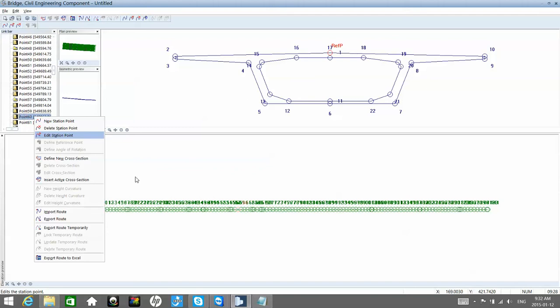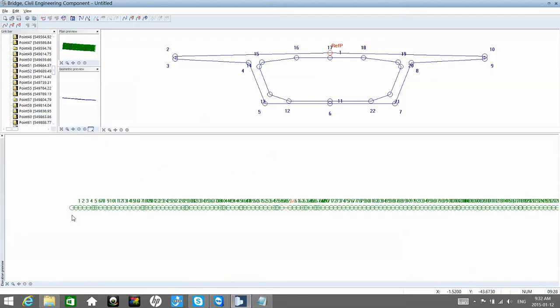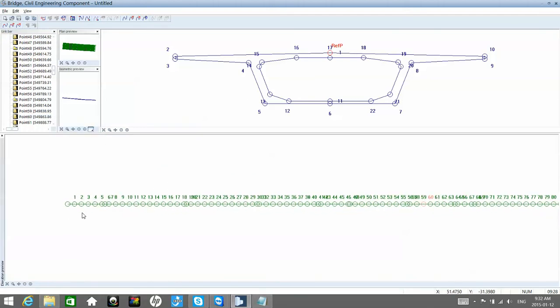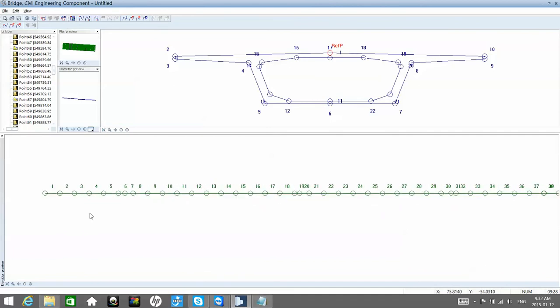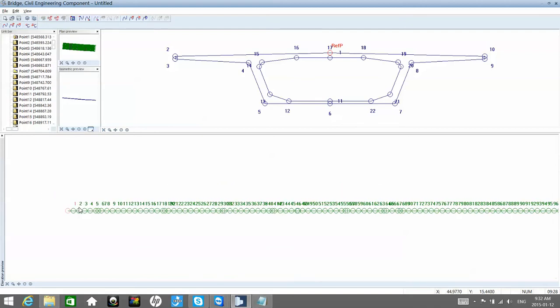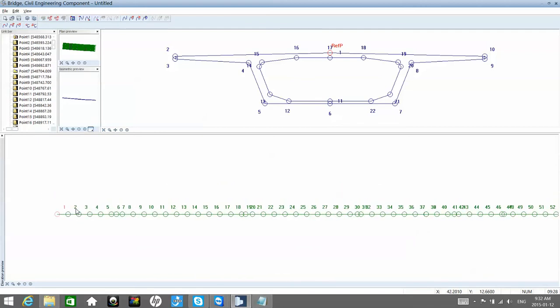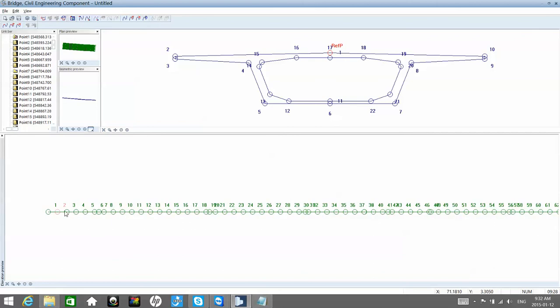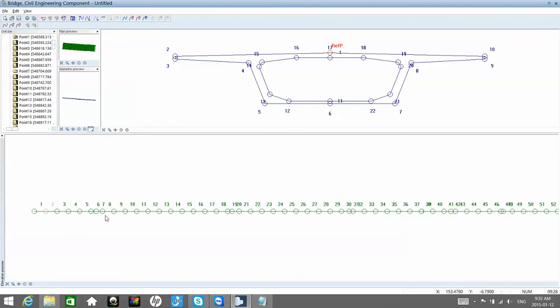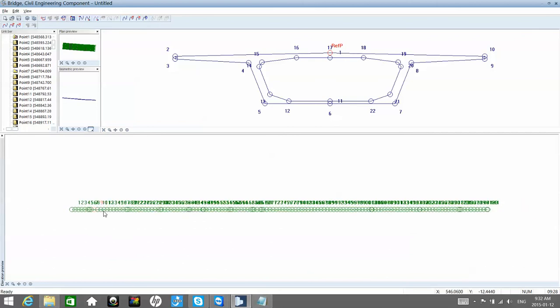Well, you can only know if from the beginning you do these divisions by points. And normally when you receive from the ones who designed the road, you get this numbering of points. These are called pickets or key points, and these are given by the one who designs the road. So normally this numbering corresponds to the road design. They can start with a different number than ours, but it will be basically the same.